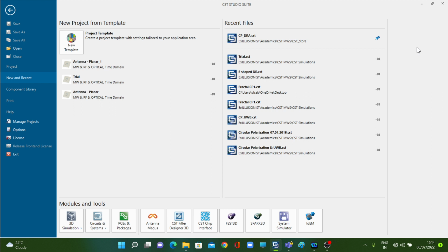The two others, that means HFSS and FEKO, have some shortcomings in terms of the frequency range in which they can provide accurate results. For example, the High Frequency Structure Simulator can give you very accurate results if you are simulating over high frequencies. FEKO is comparatively a newer one, so it is yet to be tested for its credibility in electromagnetic simulation.